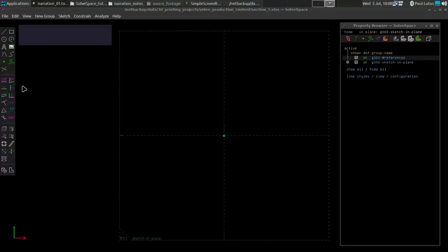Okay, big toolbar over here. The top section of the toolbar are drawing commands, lines, squares, circles, and so forth, that are applied to your two-dimensional sketch. Next, we see a whole bunch of constraint applying commands, which you use to describe the lengths, arcs, and angles, and so forth, of your drawing. The lower section is, as I said before, the area that has the extrusion commands that take your 2D sketch and turn it into a 3D object.